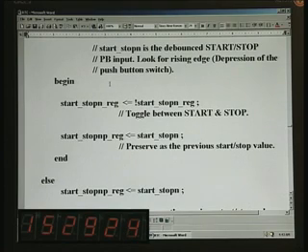And here what we should do is whenever we push the button, it has to toggle, right, because we have only one register called start stop n. The same will indicate whether it is in start mode or stop mode. The first time, when your system initializes and resets, this will be cleared, and subsequently when you push the start button once, this will be made 1, and subsequent pushing will have to be inverted.